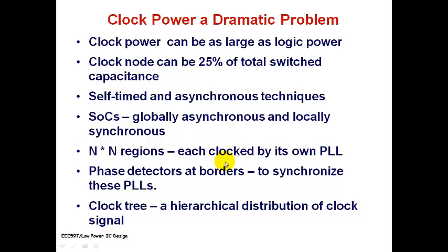Similarly, if I need a very high speed performance, go for working at higher voltage. If the speed is not so important, and power is the main factor I am concerned about, then go for working with lower voltage. This is the trading that we had discussed even at the starting.